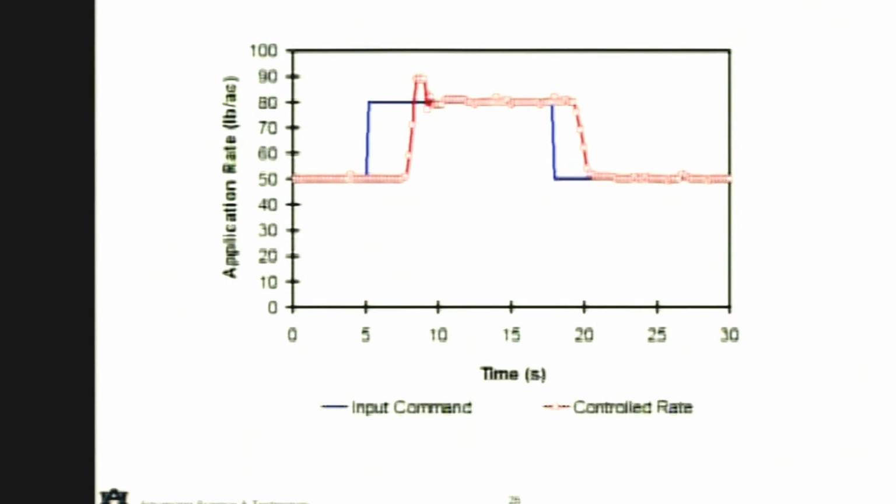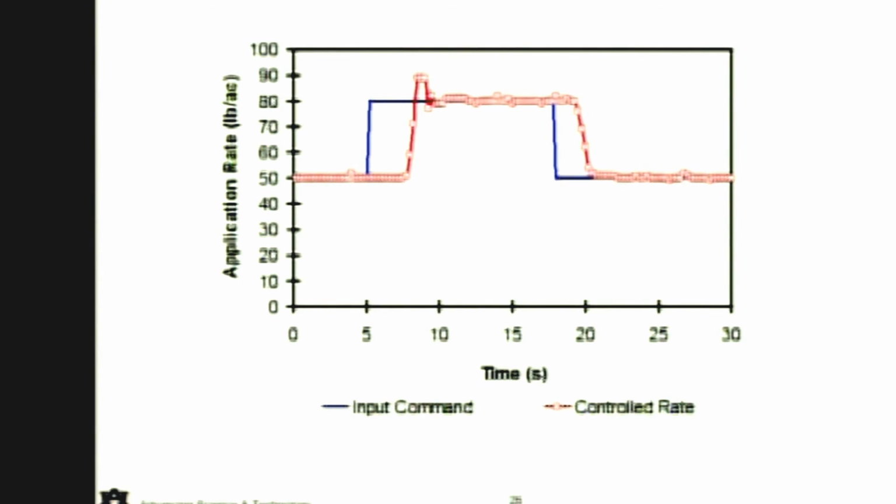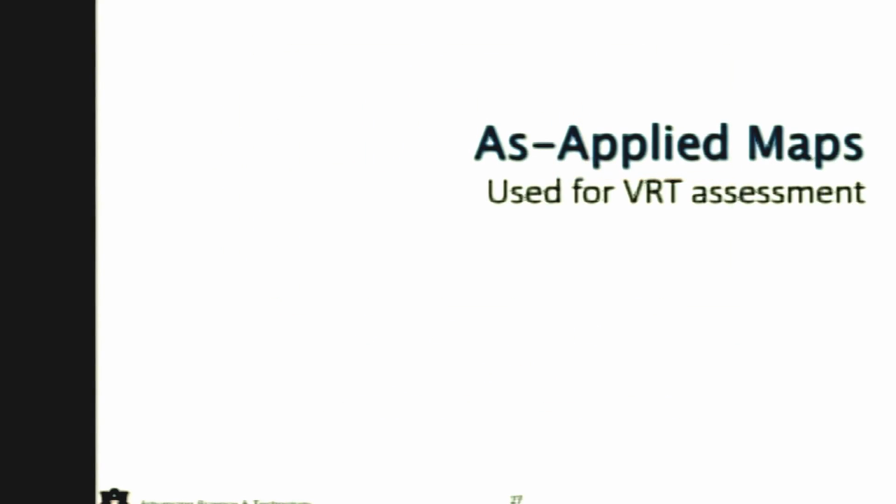systems. So with that, the last thing I'll say about that is not everything happens instantaneously, but there's a benefit in most of these systems to set what we call a look-ahead time. We just shift to make sure that rate change occurs. So again, a look-ahead time is a value. Typically in most of these it will be somewhere on the order of half a second to 3 seconds, depending on the implements. And most of your dealers or equipment companies can really help you know what that value should be.